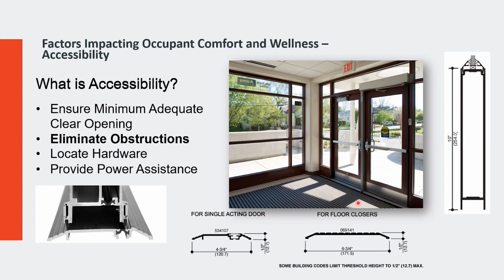Also notice here in the center, right at this point, there's a removable mullion. So if we have to open these doors, prop them open to get something larger through the door, we can very easily do that. Other key aspects to entrances regarding accessibility is the height of the threshold. If you notice in the details here, the thresholds are all limited to 1/2 inch. So according to ADA, thresholds cannot exceed 1/2 inch, again, to make it easier for wheelchairs to get in and out and over the thresholds to the interior.